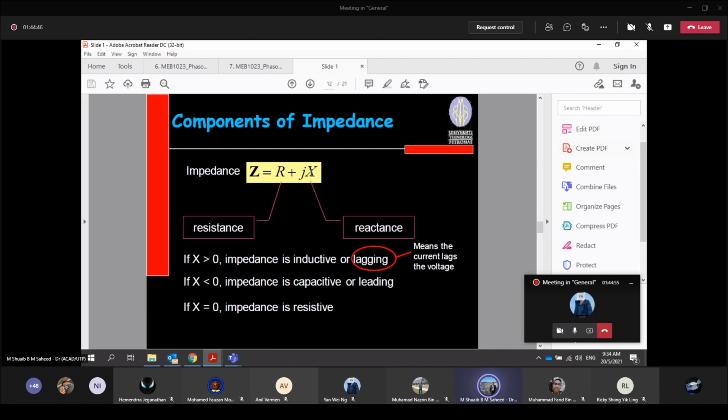So when does this happen? One case that this could happen is in the case of resonance frequency. In the case of resonance frequency, the individual reactance of inductor and the capacitor will cancel out with each other, leaving only the resistor as the active component.